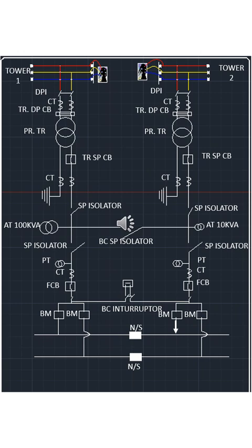Then for every electrical system, the main thing is its earthing and its isolation and charging system. For isolation, first we have to prepare the earthing system. The earthing mesh is arranged just 600 millimeters below ground level, and all system earthing and equipment earthing is connected with that grid.